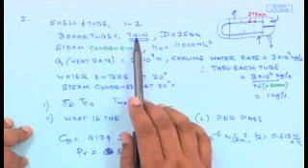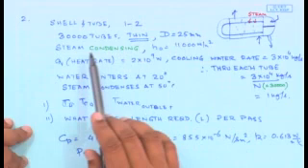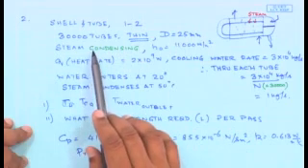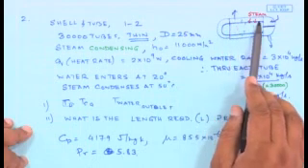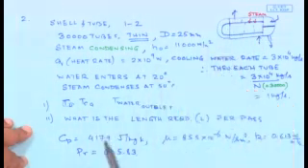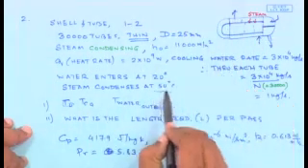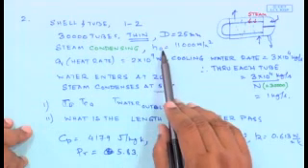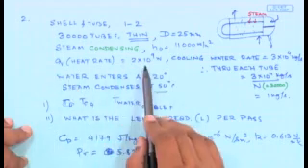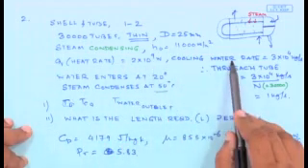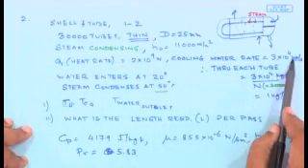So, this is a classic problem of a 1-2 heat exchanger, large number of tubes, thin, that means no conduction resistance, diameter is provided, steam is condensing. Since steam is condensing, the temperature on the outside of the tube is going to be a constant, which as mentioned is 50 degree. The value of the heat transfer coefficient is quite high on the outside. The heat to be removed is specified. The cooling water rate is provided.